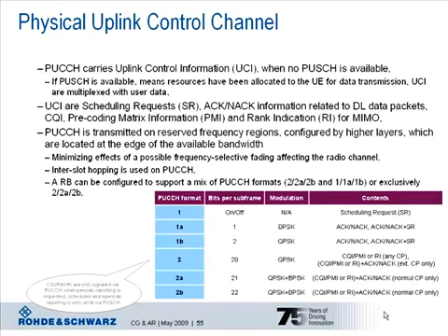The physical uplink control channel is transmitted on reserved frequency regions, meaning the lower and upper edge of the available spectrum. This minimizes the effect of possible frequency selective fading affecting the radio channel. Further, interslot hopping is used for the PUCCH. That means the transmission jumps from, for example, the lower edge of the available bandwidth to the upper edge within one subframe. This is also to ensure that the uplink control information arrives at the eNodeB. Depending on the information to be transmitted, different formats are used as shown in the table, using different modulation schemes and a different number of bits.